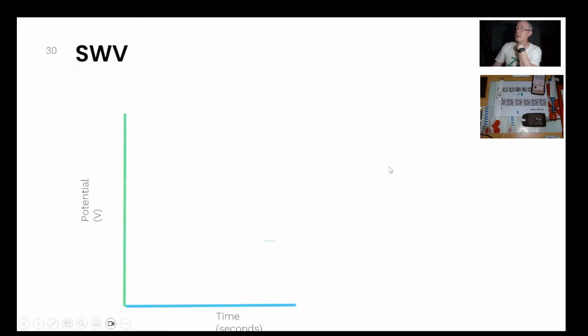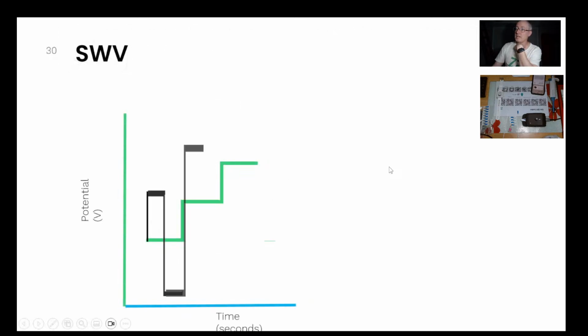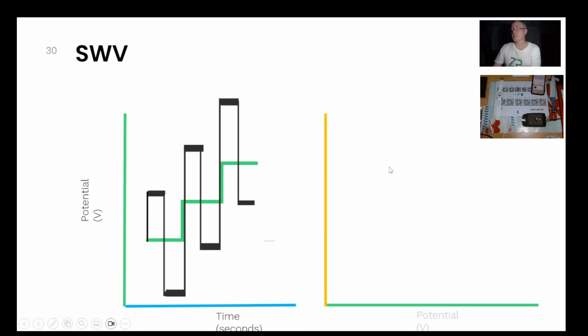And they're actually sampling in 2 places. They've got something called the forward. So I sample here. So I'm timing, because in fact I didn't collect the data at the beginning of this pulse. I collected it near the end of this pulse. And it's the same with the reverse, forward and reverse they call it. And I'm also filtering by timing, because in fact I collect at the bottom, at the end of this 50%.